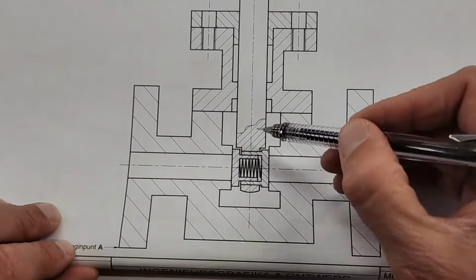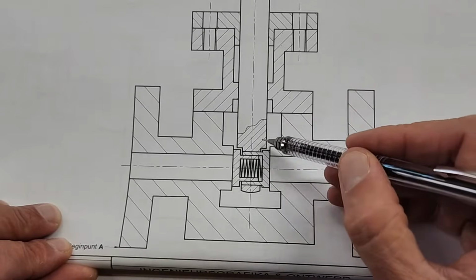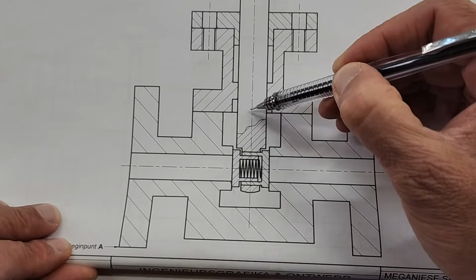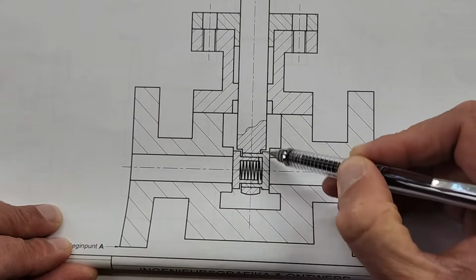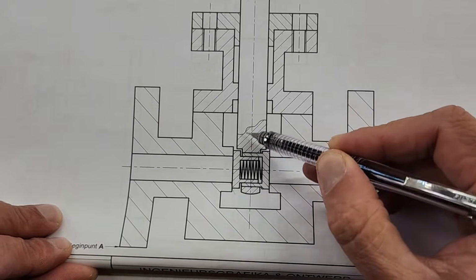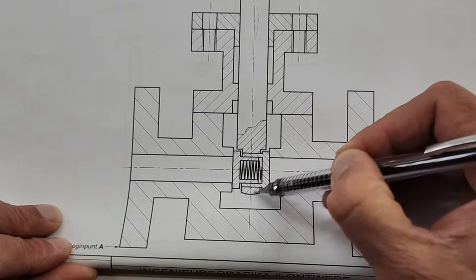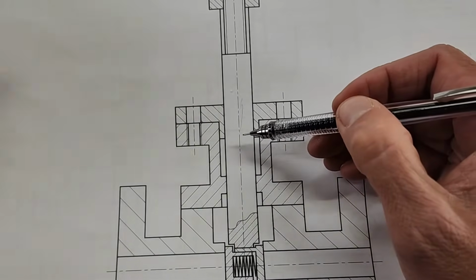If it's not specified, why would we hatch this? We would hatch this because it will give us more insight and information into this. Although this is a shaft, hatching this gives us more insight into what happens here in the middle. And so you won't hatch the entire shaft, just the part that actually is going to help you with more information. If I hatch this part here, that would have been absolutely meaningless for me.